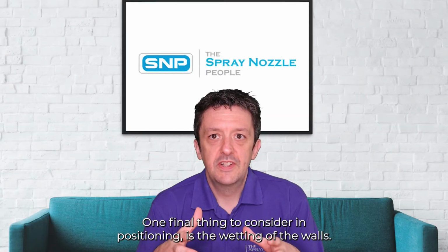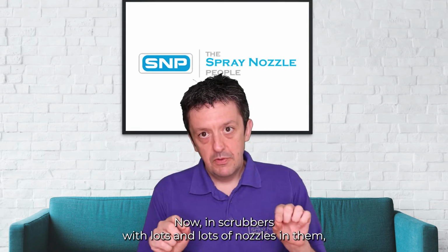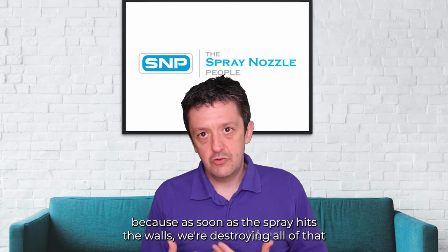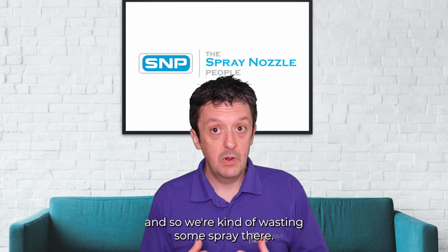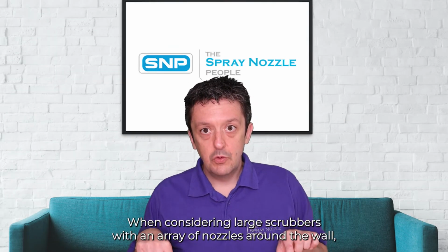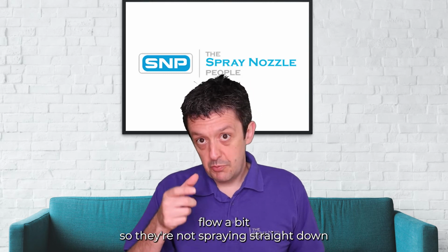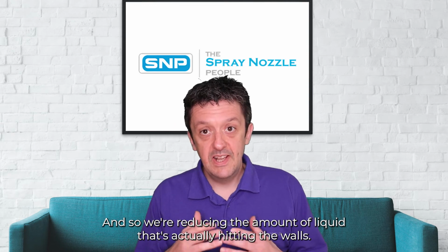One final thing to consider in positioning is the wetting of the walls. In scrubbers with lots and lots of nozzles, we're inevitably going to end up with some of the spray on the walls, and this is a waste, because as soon as the spray hits the walls, we're destroying all of that lovely drop size and atomization, removing all of that surface area, and so wasting some spray. When considering large scrubbers with an array of nozzles around the wall and many in the center, we may want to angle the ones around the wall into the gas flow a bit, so they're not spraying straight down or straight up, but at an angle, reducing the amount of liquid that's actually hitting the walls.